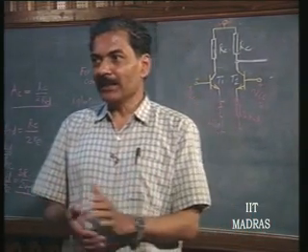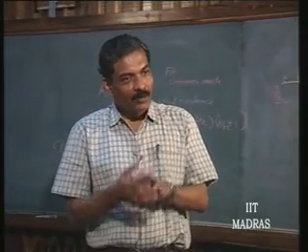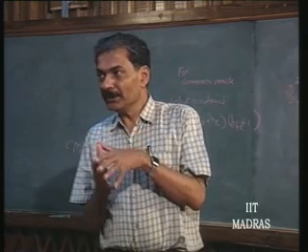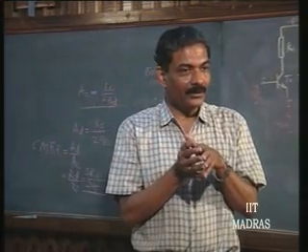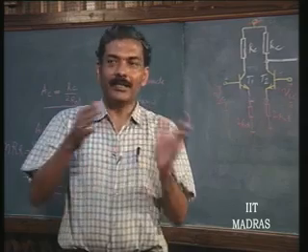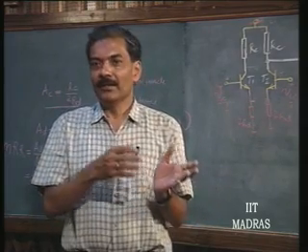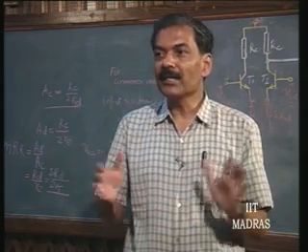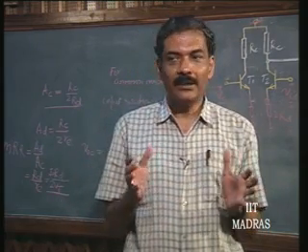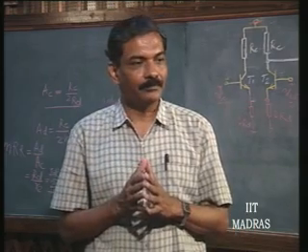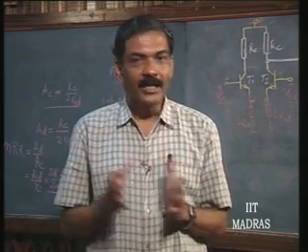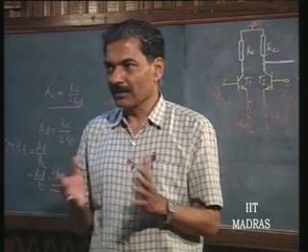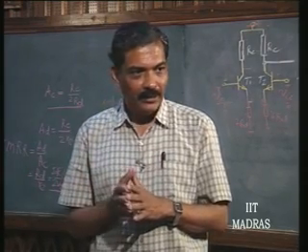As far as large signal property is concerned, once again, common mode swing at the input, differential mode swing at the output, which is nothing but I naught into RC, and the relationship between VID and V naught D, which is nothing but the tan hyperbolic function. These are the things that you have to remember in the case of any differential amplifier. Clear?